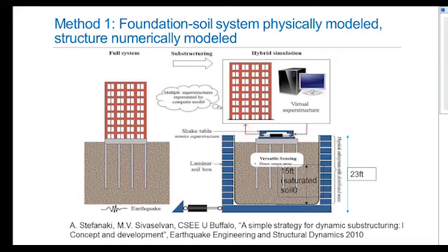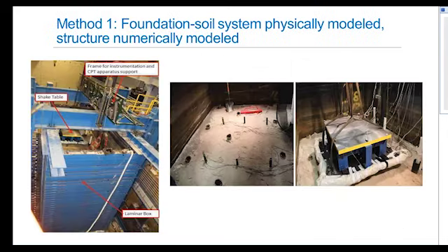And the piles themselves were explicitly modeled as well, of course, as the soil. The interaction between the tested structure and the numerically modeled structure was done through this shake table that's placed on top of the foundation slab.